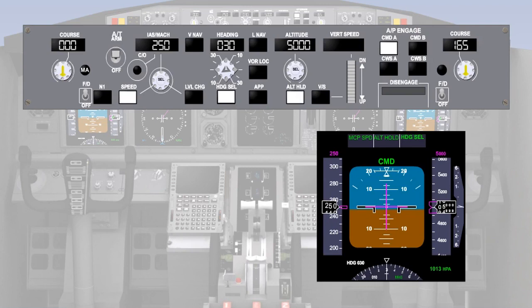These two are referred to as compatible modes. Modern autopilots will not accept incompatible modes. For example, altitude hold and N1 would be incompatible, as neither the autothrottle nor the pitch channel of the autopilot is maintaining the speed of the aircraft.